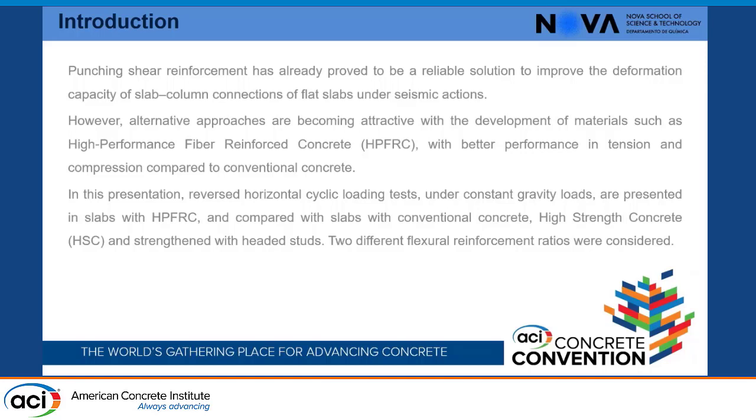But new materials are being developed, and we, inside the project, developed a high-performance fiber-reinforced concrete that has better tension and compression performance than conventional concrete, and tested it in these connections.